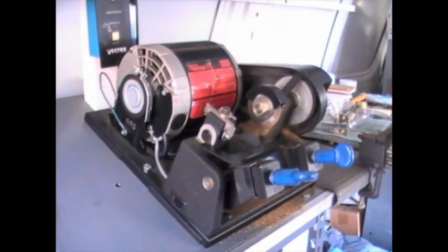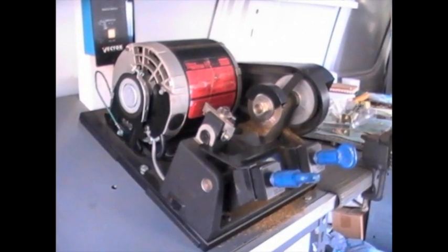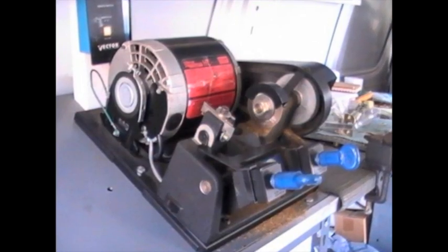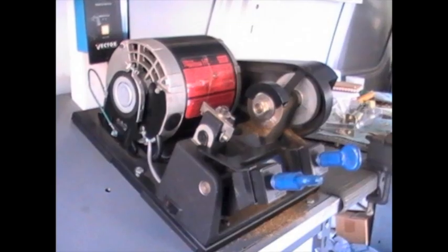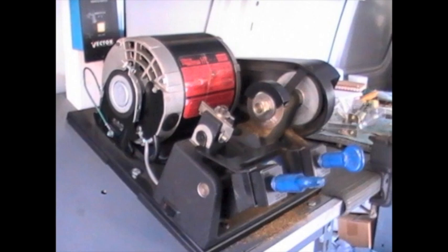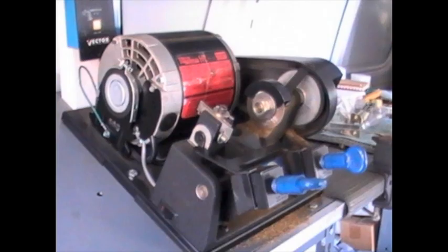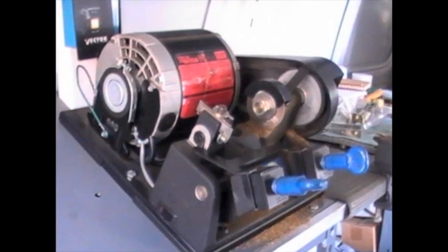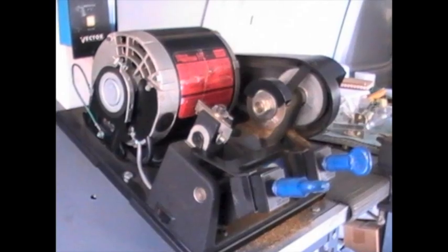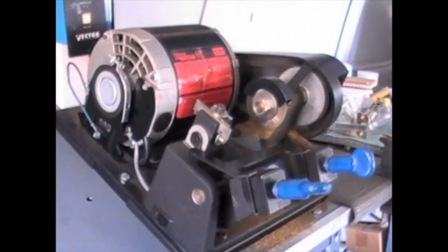Okay, at the front of the van, the cable that supplies the battery with power is actually hooked to a solenoid. And so when the van's not running, the key machine and the lights do not draw power from the van, the battery that operates the van. That way I don't need to worry about running down both my batteries and not being able to start my van. But when I start my van, and I'm driving down the road, then the battery that runs the key machine will be charged.